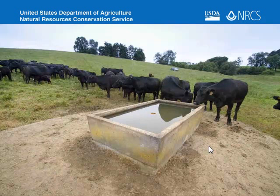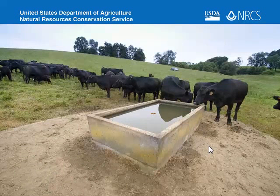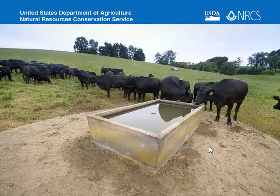Just what I wanted to mention about this is just last year we went to a site to look at an NRCS design and installed tank, and instead of being 24 to 32 inches off the ground for cattle, it was at 37 inches.